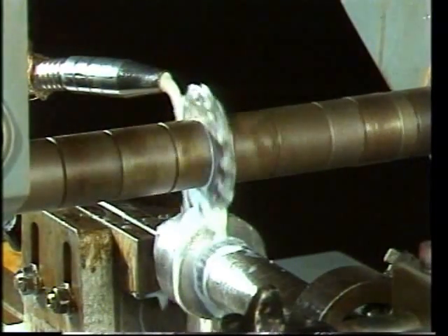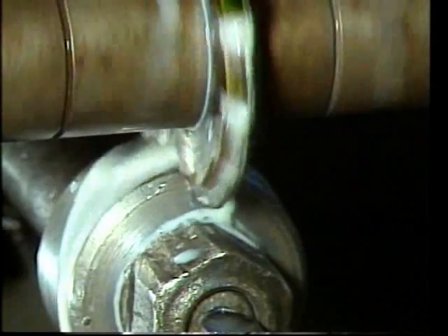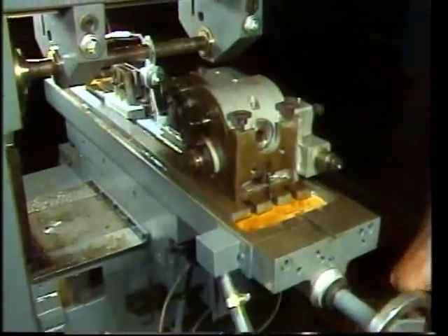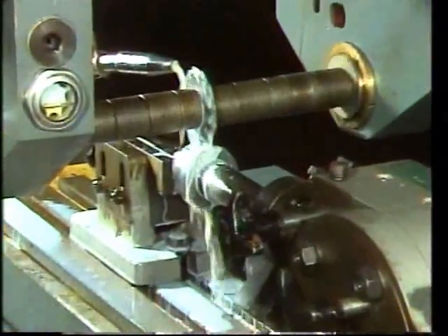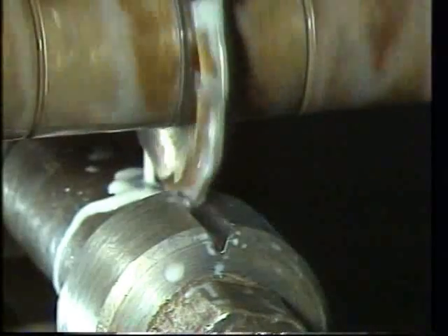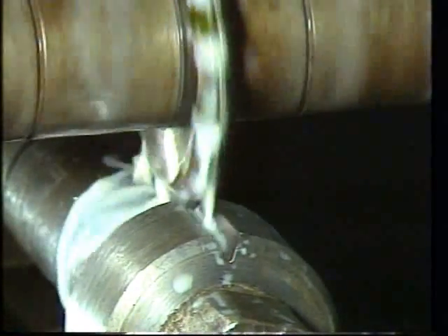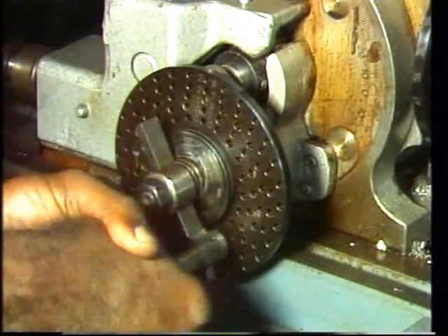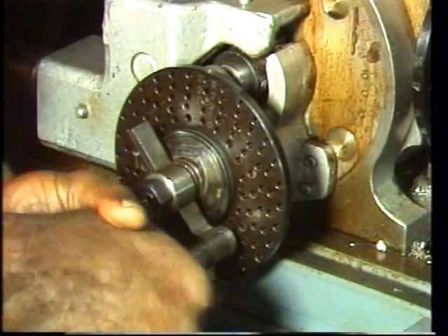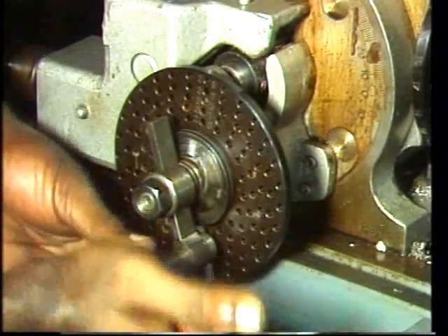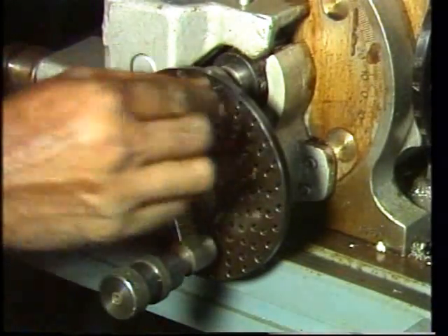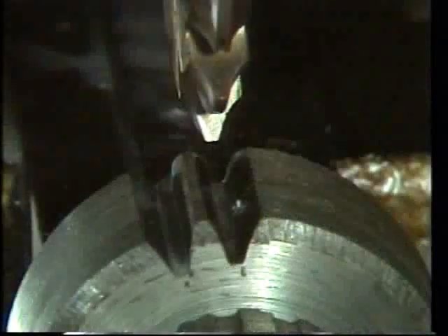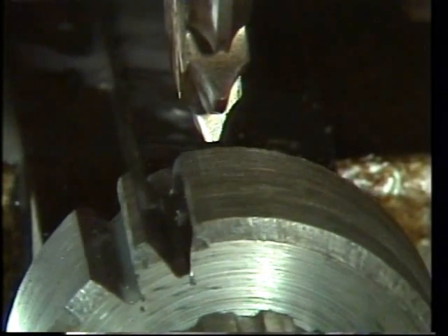During cutting operation, cutting oil lubricant is used in order to keep the cutting edges of the cutter cool. On the completion of one rough cut, approximately 3/4 of the total depth, the job is indexed for the next tooth. The operation is repeated for all the teeth.